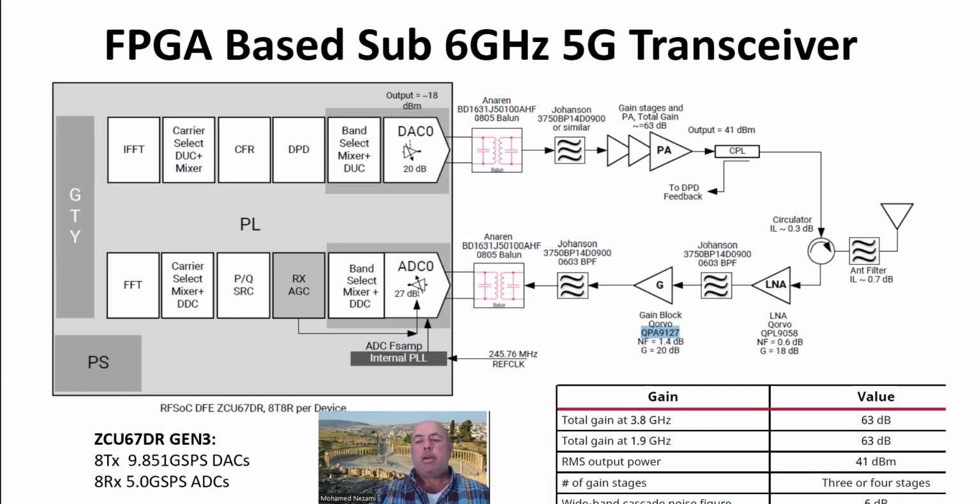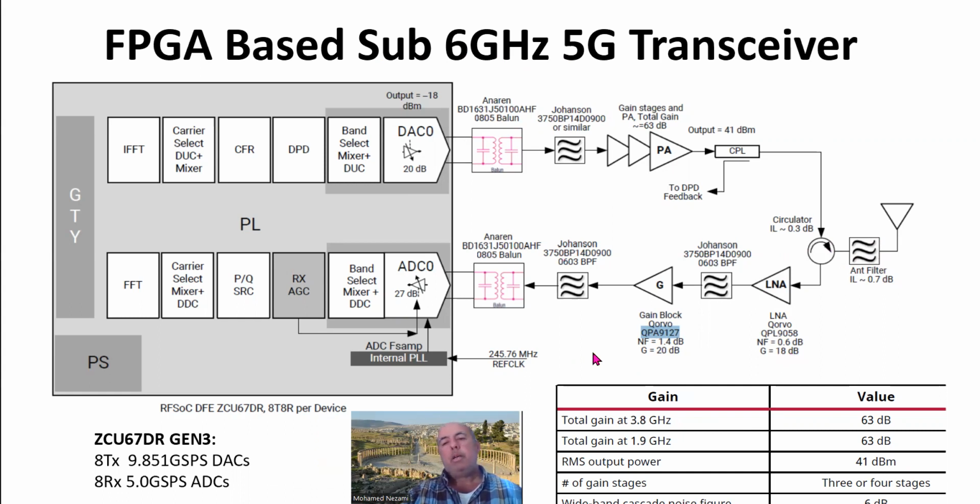In this case, we really have about 6 dB, primarily because we have a filter, a circulator, and an LNA in the sub-6 gigahertz range. That's unlike the devices available for Ka bands. But that's good because we don't care anyway.